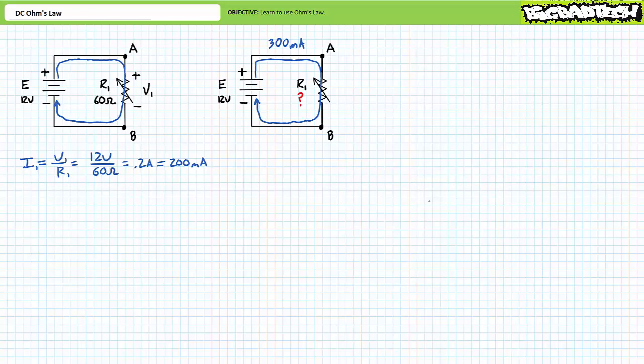Think about it. No numbers, just think about it. Voltage stayed the same and current increased. Did resistance, or opposition to current flow, go up, go down, or remain the same? If you're tracking, you should realize that resistance has decreased. A simple Ohm's law calculation supports this assessment. Resistance is voltage over current. An application of Ohm's law demonstrates 12 volts over 300 milliamperes yields an anticipated resistance of 40 ohms. Resistance did indeed go down.